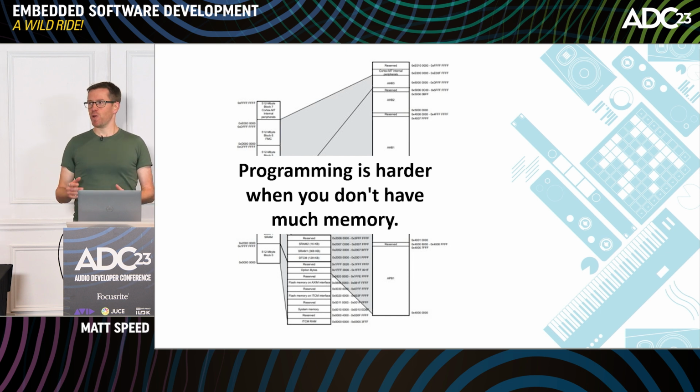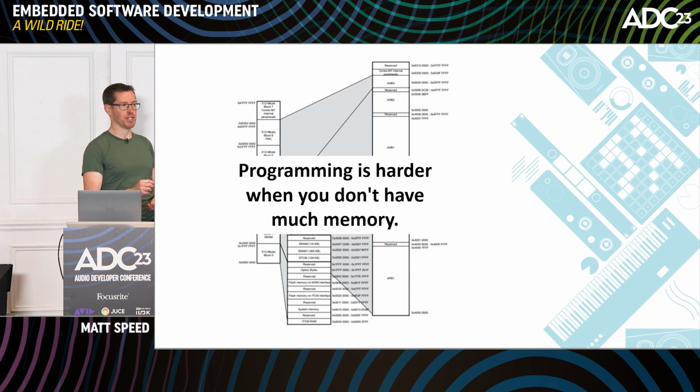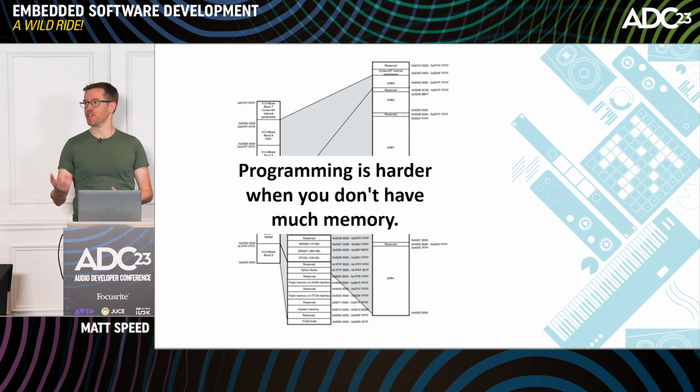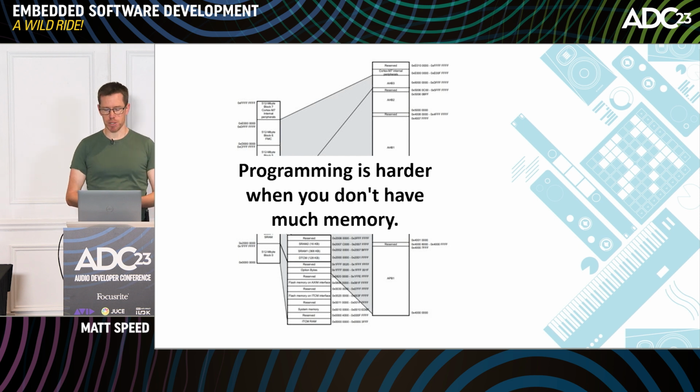As programmers, we're pretty hardwired to think about computational complexity in terms of processing time. Like when somebody says, what's the big O of this algorithm, you're immediately thinking about the kind of processing cycles it will consume. In embedded, a larger concern is probably memory complexity. Because you can write the fastest algorithm in the world, but if it doesn't fit on your micro, it's absolutely useless to you. And memory becomes a much bigger concern.